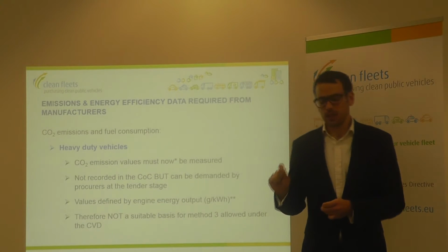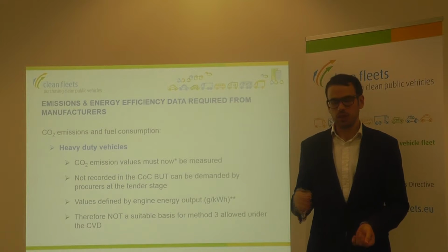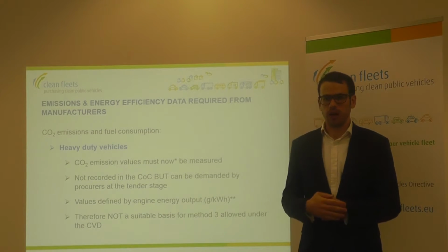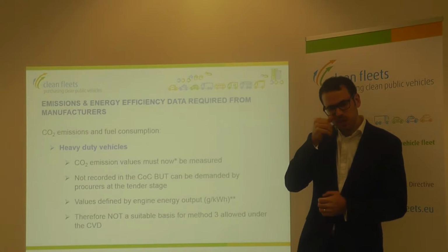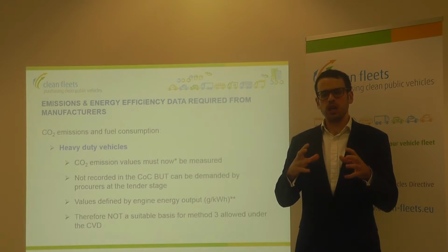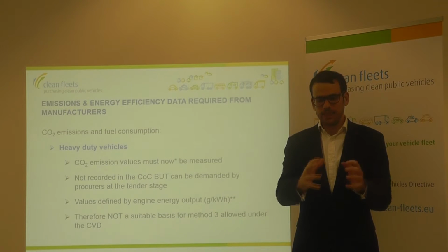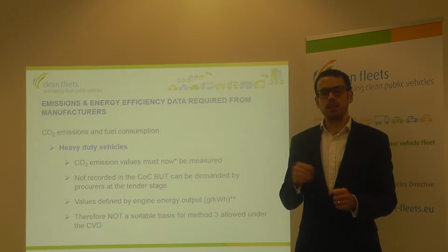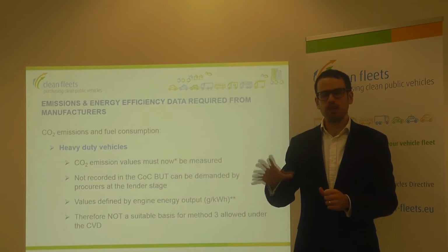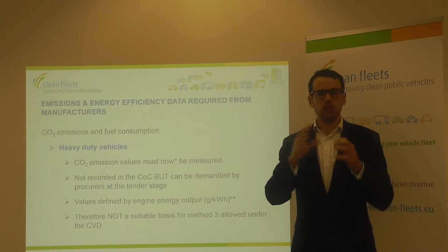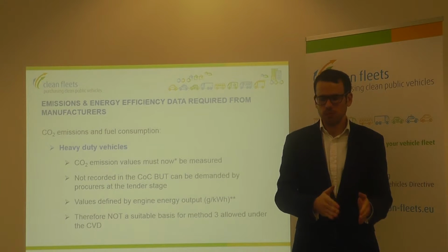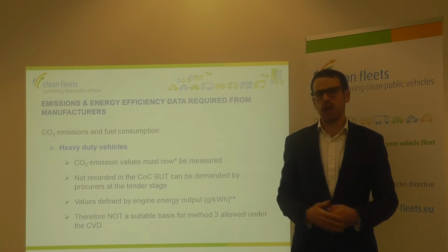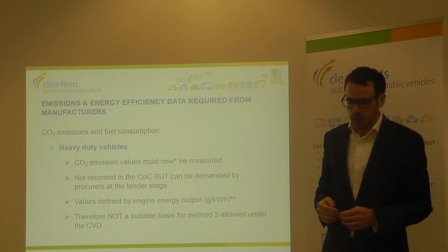Now, the other difference between a heavy-duty vehicle and a light-duty vehicle is that it's not grams per kilometre, it's grams per kilowatt-hour of CO2. Part of the reason for doing this is because they measure one engine, and then that engine can be used for a number of different applications. An engine that works in a bus is going to have a very different CO2 profile to an engine that works in a truck doing 70 kilometres an hour all day long, compared to a bus that stop-starts, never getting over, say, 50 kilometres an hour.